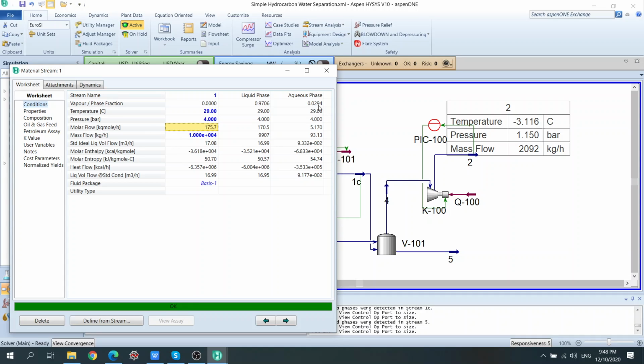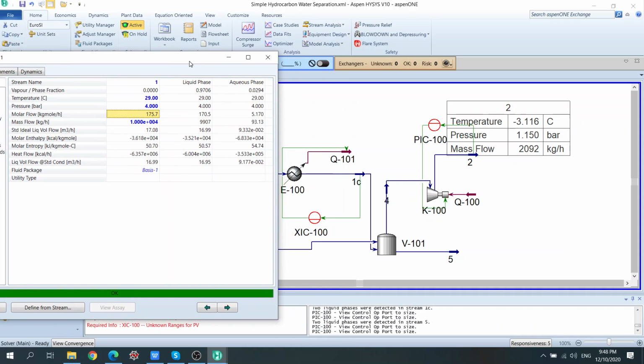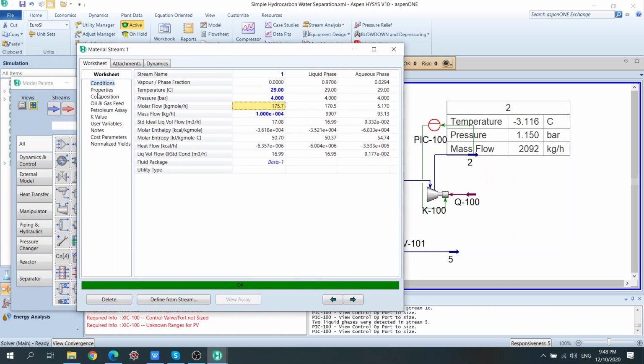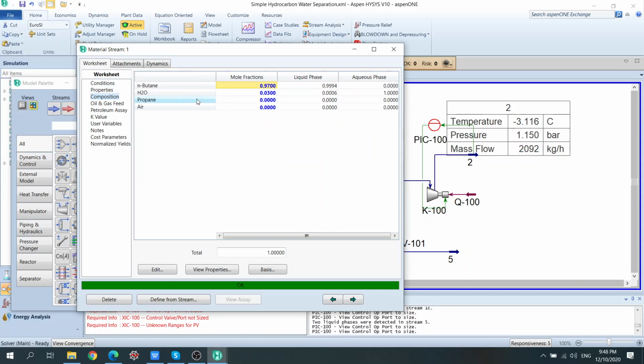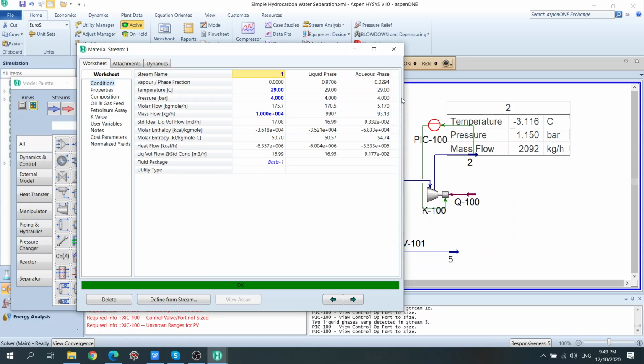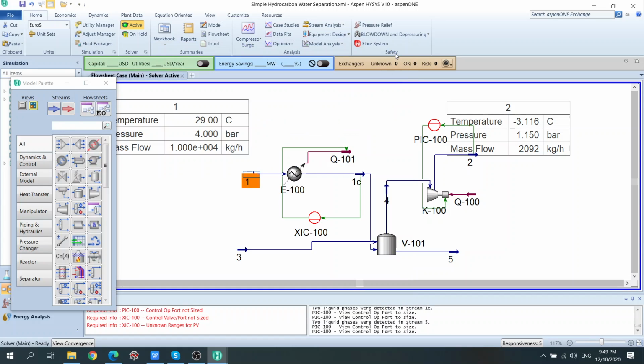In this case, it already has liquid, but it's two phases: the liquid phase for the butane, and the aqueous phase. Do you want to separate the water from the liquid hydrocarbon, or just combine them as liquid?